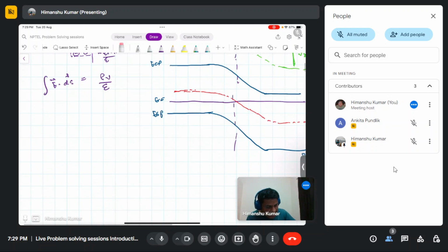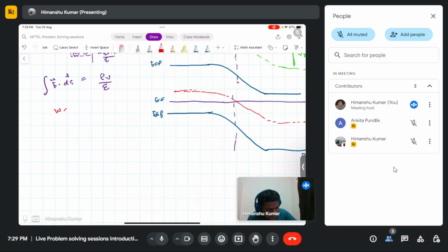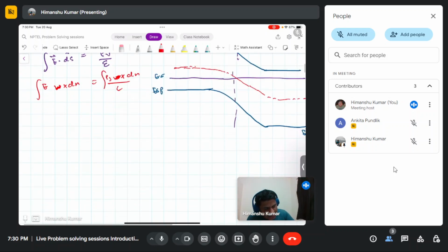So basically this area cross section you can write as width of the device times dx, and this is your cross section area times E, and integrate. You can write this as width times dx times the density, or you can calculate the volume charge density to the surface charge density, and if you normalize by this width, then you have the surface charge density times dx by epsilon. And if you take the derivative, this is integral of sorts.